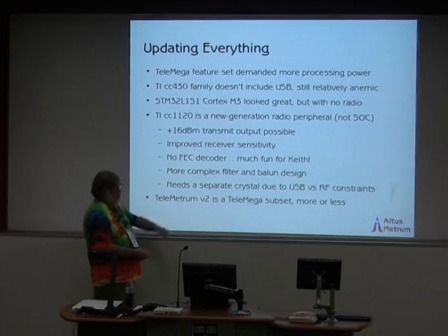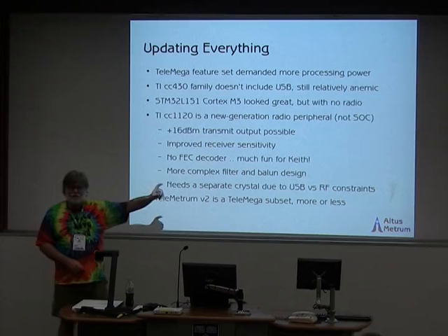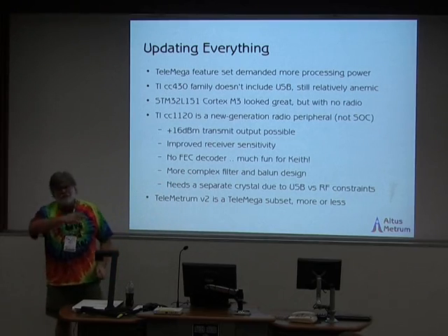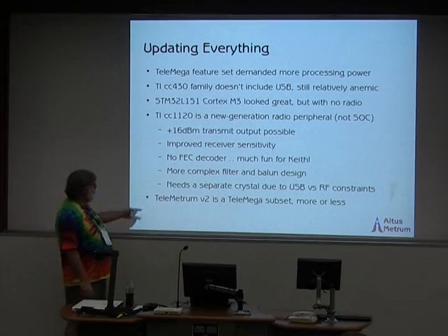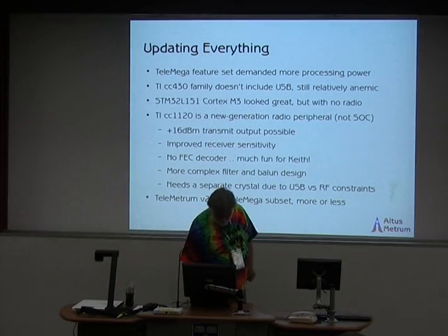We end up using 2 crystals because the ST part wants one crystal frequency to make USB work right, and that's not an easy one to also use for the radio. And we ended up using that for the new board.